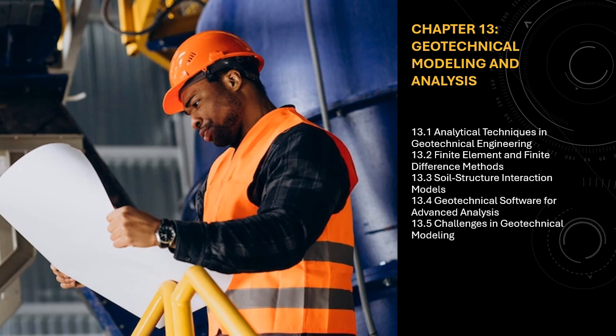3.1.3.1 Elastic plastic models. Elastic plastic models are commonly used in geotechnical engineering to describe soil behavior, particularly for predicting the yielding and failure of soil under high loads. One of the most popular models in this category is the Mohr-Coulomb failure criterion, which is widely used for understanding soil shear strength and for analyzing foundation stability and slope failures.